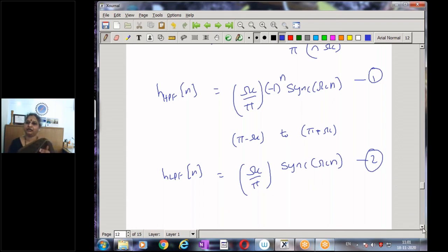This is like in analog filter design. Suppose I have designed an analog low pass filter, a filter which includes a number of resistors and capacitors. I need to convert the low pass filter to a high pass filter. We just interchange the resistor and capacitor. The same filter now becomes a high pass filter. Exactly similar in the design of discrete digital filters, I can convert a low pass filter to a high pass filter by changing the signs of the alternate terms by using this important result, minus 1 to the power of n. So this is the first step, computing the coefficients.